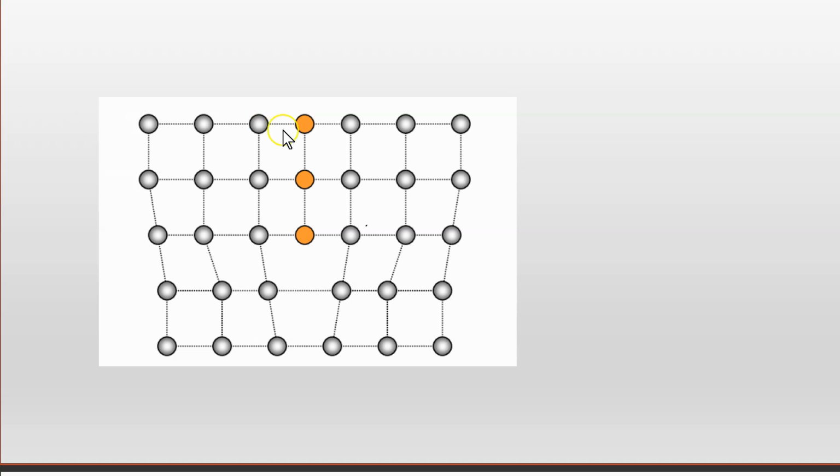Then we want to pick a loop that goes around the dislocation, and let's pick a start point. Let's say we start here, and I'm going to make a rectangular path, which in a perfect crystal should come back to the start position. So let's make 1, 2, 3, 4 steps here. Let's go down 1, 2, 3, 4 to completely encompass this dislocation.